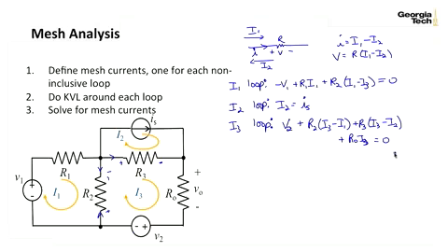So right now I've got really 2 equations and 2 unknowns because I2 is known. I'm assuming my source is known. So I2 is known. Wherever I see an I2, I substitute in I sub s, and then I just end up with 2 equations and 2 unknowns, and I can solve that for I sub 3 and I sub 4. And once I solve for I sub 3, I can go back and solve for V0.